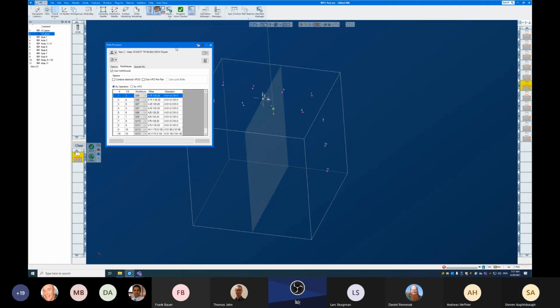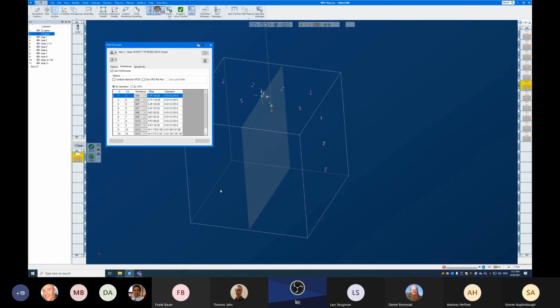On Monday, I sent a part to Steve to show it here because I got a question concerning 3D material only or material, the new option. I came across a case at a customer where I wanted to extend the toolpath by entry-exit moves, and it didn't work when round corners wasn't active, but as soon as I activated it, it worked.